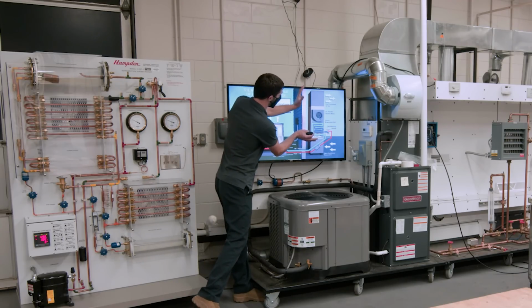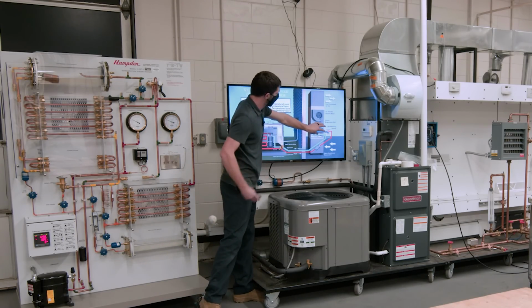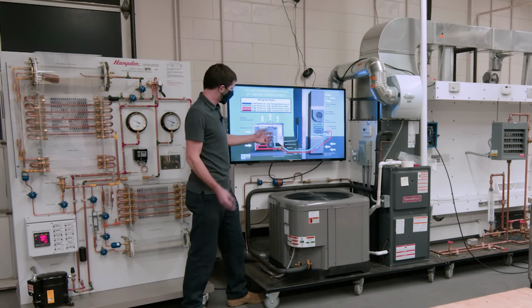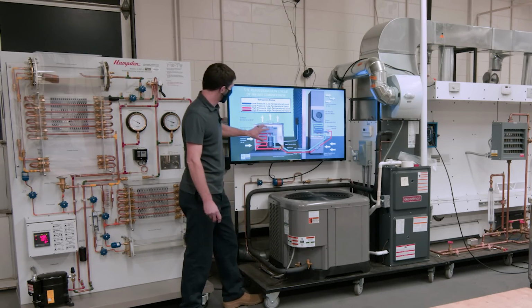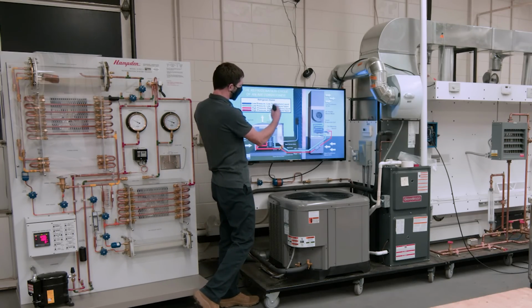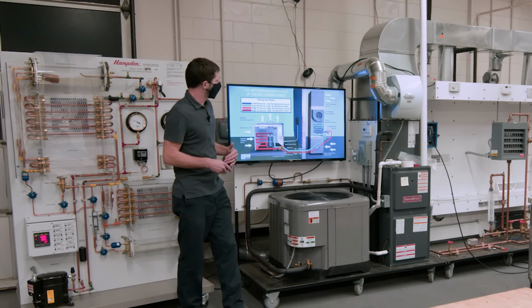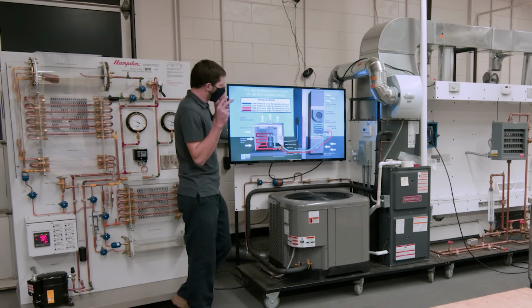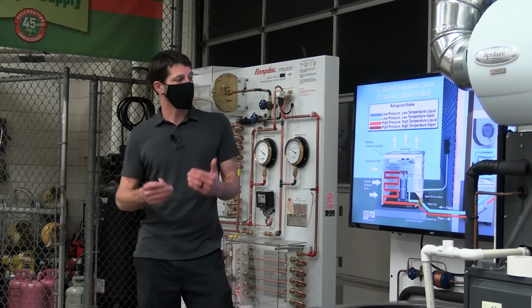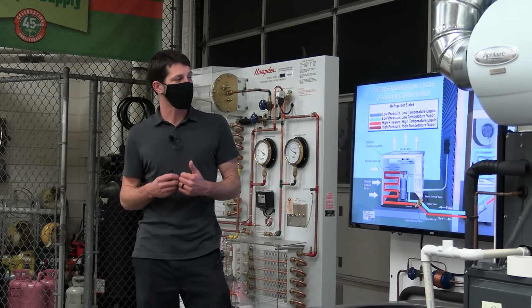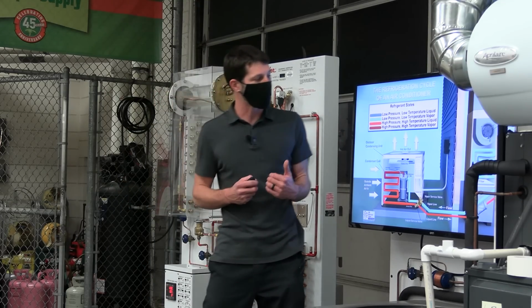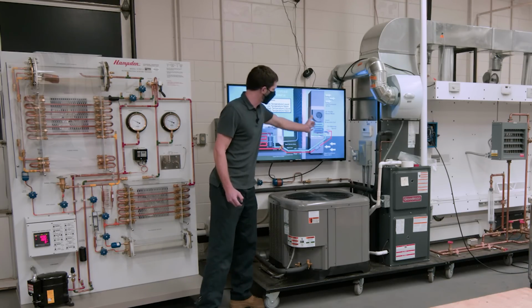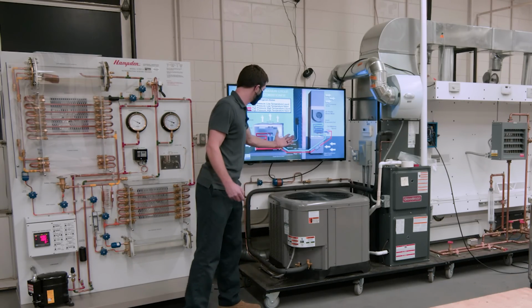What's happening here is you're absorbing heat into the refrigerant inside the building. The refrigerant is moving that heat, storing it, and bringing it over to the outdoor unit, where you reject the heat. There's no such thing as cooling a building, even though you say cooling mode. It's your air conditioning mode, and what you're doing is lowering the temperature inside the building. Of course, you're also taking the humidity out of the building by attracting it onto the coil, and it drips down and out to a place like outside.